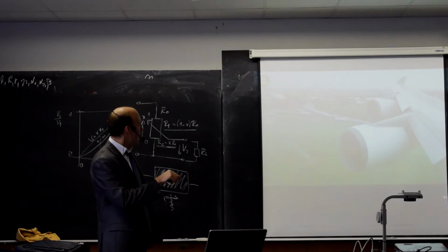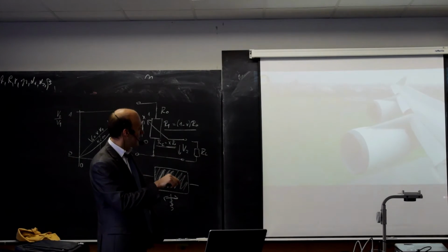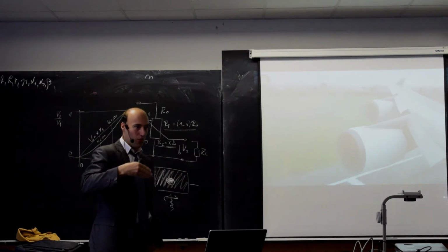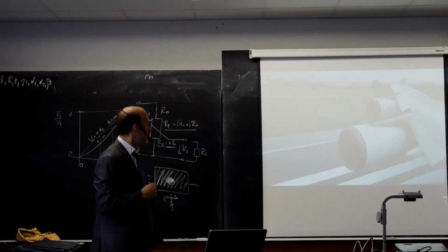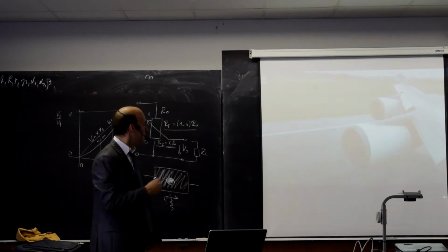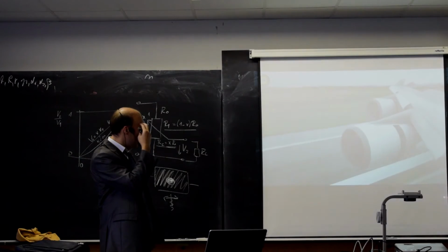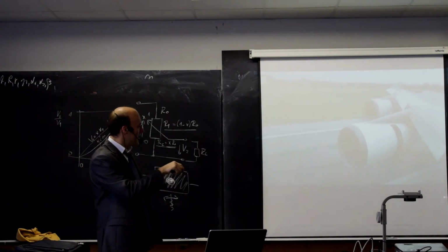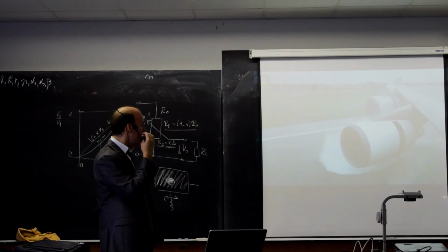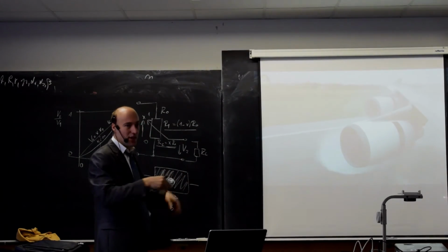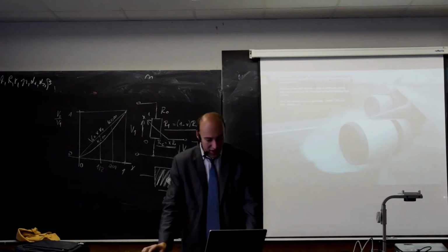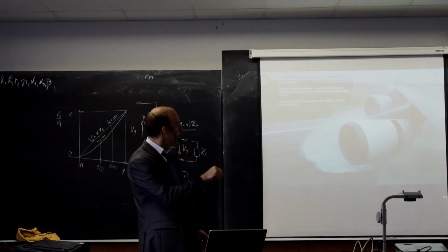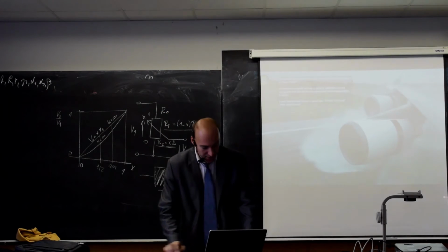When the airplane lands, you will see that a slit will open, and that's what is redirecting the thrust against the motion. Later I have some other video as well. And this is how the airplane brakes. Now the position of this mechanism is sensed by an LVDT. You see the thrust of the airplane is going against the motion, where they are using LVDTs to sense the position of this mechanism.